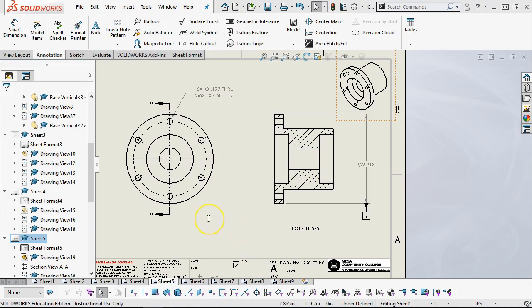All right, so the 40 millimeter OD and the 17 millimeter ID. So this is where we would come back to that tolerance and looking at the ID tolerance of minus 0.007 millimeters. So keep in mind that that's, here we go doing math again. That's very small.